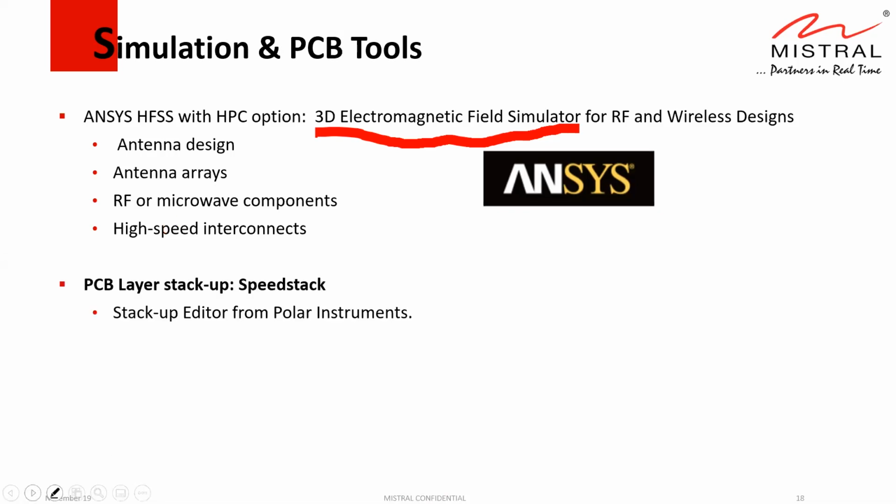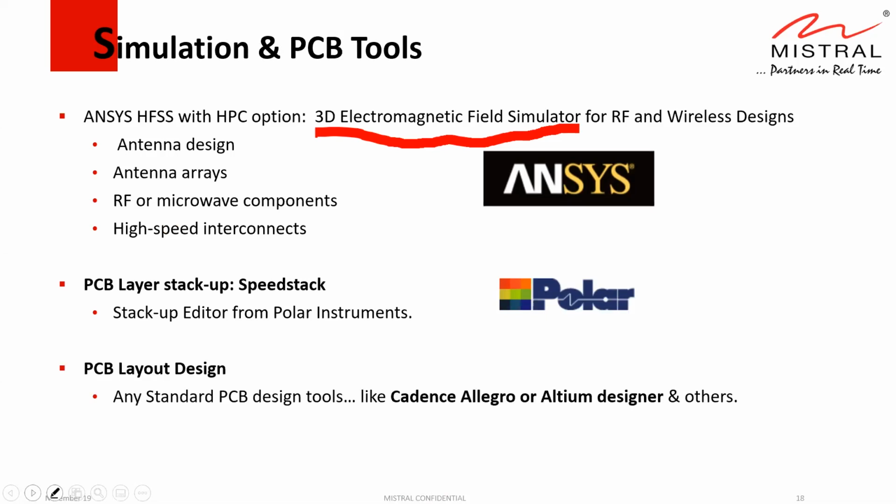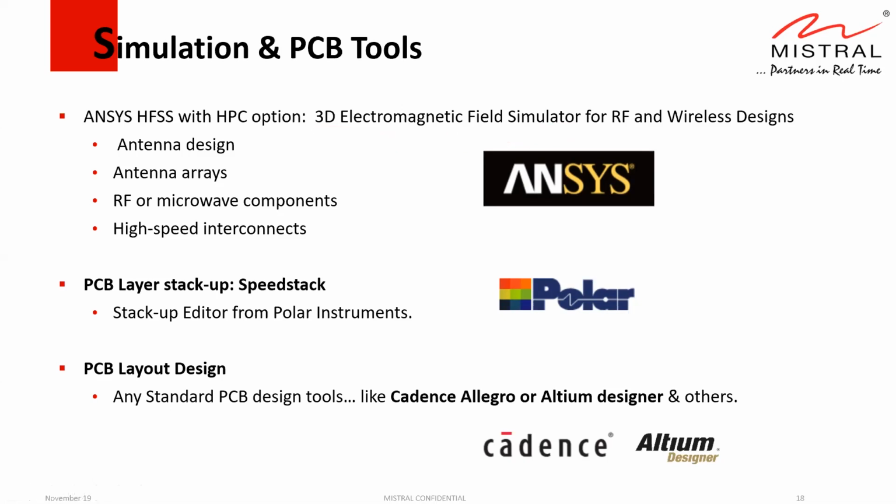And for the PCB layer stack-up impedance calculation, there is a generally universally used tool. You can go with Polar, the tool called Speed Stack. And for the PCB layout design, any standard PCB design tools can be used: Cadence Allegro, Altium, or PADS. Any tool can be used here. There's nothing specific.